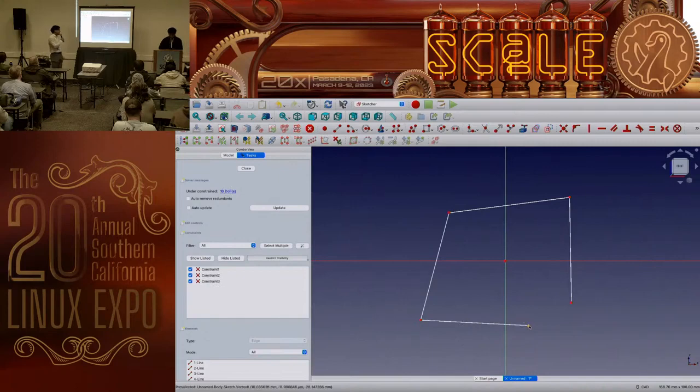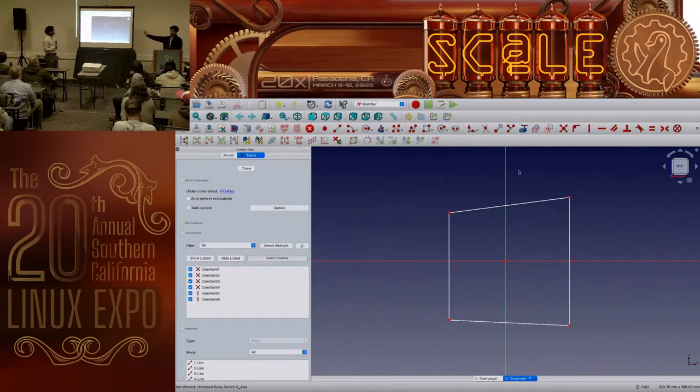And as you guys notice, as we're connecting these lines, there's something wrong with these lines. What are they missing? They're not straight, right? It's not a square yet. Okay, so using our constraints, we're going to make our lines straight. So we're going to use constraint vertically. What this does, simply click a line, and now they're vertical. Obviously, we need to do that horizontally as well. So we'll click horizontal, and now we have a perfect square.